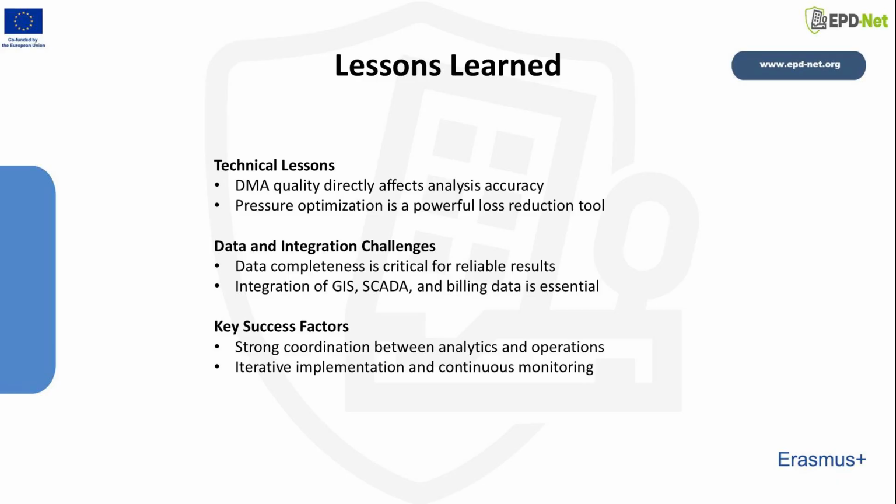The UKIP case study provides several important technical lessons. One key insight is that the quality of DMA design and configuration has a direct impact on the accuracy of analytical results. Poorly defined DMAs limit the effectiveness of leakage detection and pressure optimization.